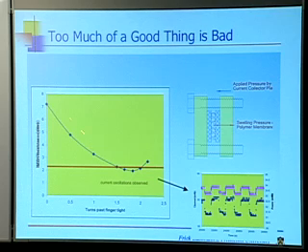And the argument is as follows. We have our two big chunks of electrode material with the bipolar plates, the big graphite sheets in there, and it's all bolted together with these huge bolts. And we have our poor little MEA squashed in there. Now, as we start up that cell and we start to generate water, if the bolts aren't too tight, the material will swell and things will get tighter.